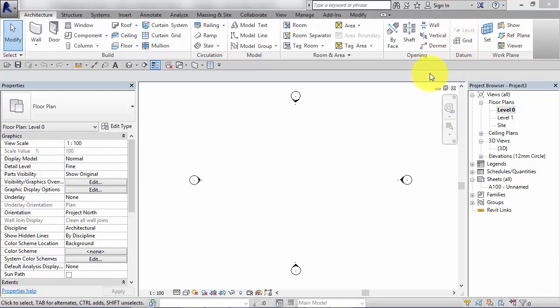As you start to get more comfortable with Revit and you start to learn where these different tools are, either you've added them to the quick access toolbar, you use keyboard shortcuts, or you just get used to what tools are on what panels, you can actually minimize or collapse some of this screen here to give you more room in which to produce your model. If you look at the right hand side of the menu tabs, there's a little button here.